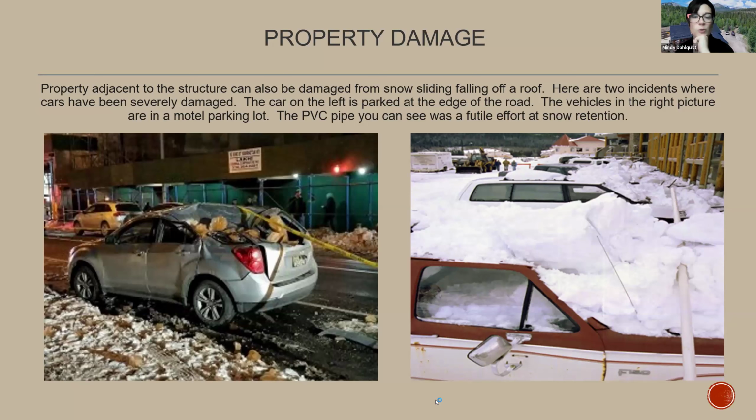Photo on the right, PVC pipe is something that we see on the roof very often as an attempt at snow retention. PVC pipe should never be holding back weight in that form.